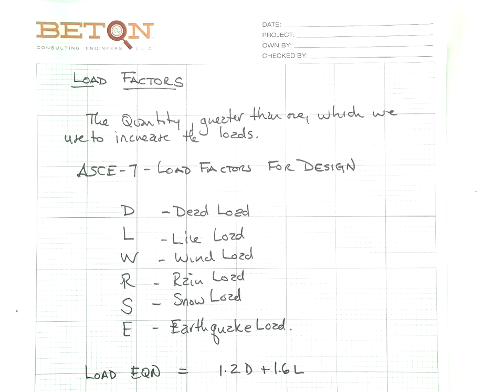and if we go to the ASCE 7, there's all kinds of combinations. And then what we'll do is say, well, this is a university, so I believe, I'd have to look it up, but I believe that it's a 50-pound dead load and a 60-pound live load is the requirement for all these buildings.